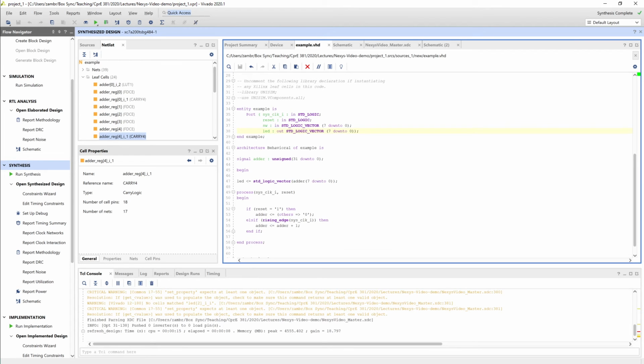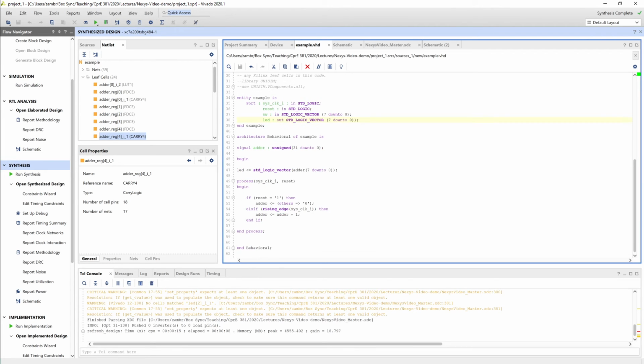And so what you actually have here is a design in which I specify a 32-bit addition, but because I'm explicitly only ever using those lower 8 bits of that adder signal that I've used here, the tools, and we could probably find a million messages that specify this, but it would take me a while to hunt them down, are going to aggressively just trim the rest of those signals. So I specified a 32-bit adder. It was smart enough to tell me, well, you didn't need a 32-bit adder. You actually only need an 8-bit adder, and I'm only going to provide you with an 8-bit adder. To me, that's a very good thing.